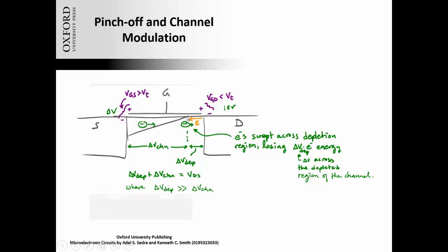And at this point here, I'm going to say that this voltage X must be at 1 volt. Okay, the voltage of the channel at this point is 1 volt. The gate is still at 2 volts. So the difference between the two is 1 volt, which is the overdrive voltage. So my channel has a depth of 0. All right. Now, as I've walked from an X of 0 up to an X of whatever that value is, I have traversed 1 volt.